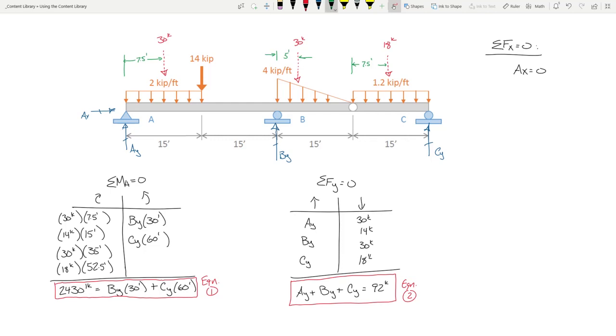Okay? So, typically whenever I cut a section, here, let me move this up a little bit. Or, tell you what, better, I'll just put this 7.5 feet over here. Typically when we cut a section, I draw my line, and then, like you'll see on a CAD drawing, I'll label it section 1-1 or section AA or something like that. So that's where I'm samurai swording or lightsabering through this section.